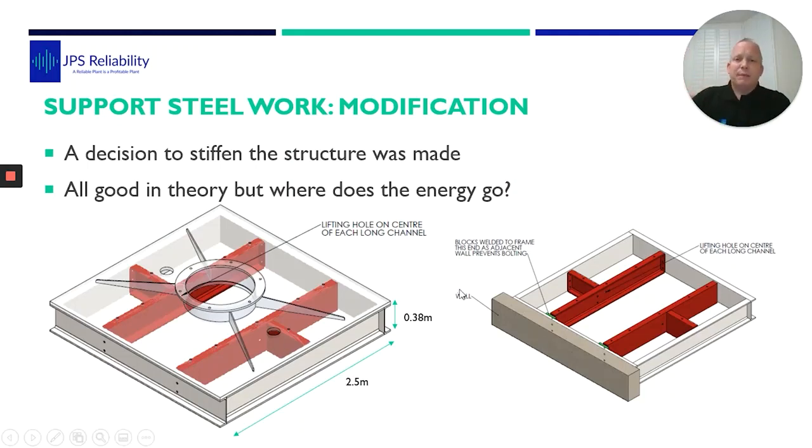well, this won't bend. They put some massive RSJs under here. So this here, bear in mind, is 2.5 meters long by 40 centimeters high. Two massive RSJs put in, drilled into the walls, bolted up solid. I did say, yep, it may work, but we're more concerned about the flange twisting. We don't want to do these big costly modifications which could cause more problems. That still could just bend, and they wouldn't have it that this is a big steel, it does not bend.